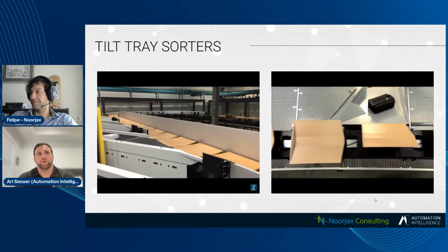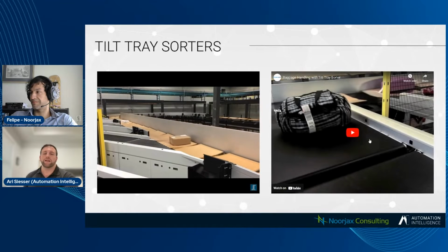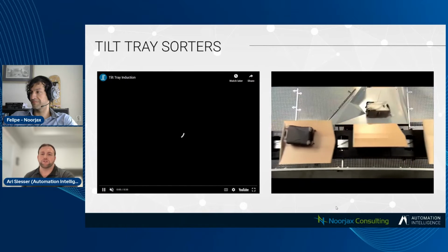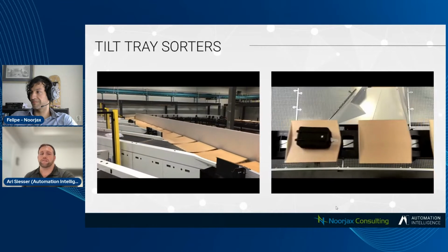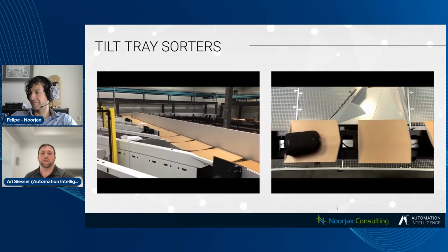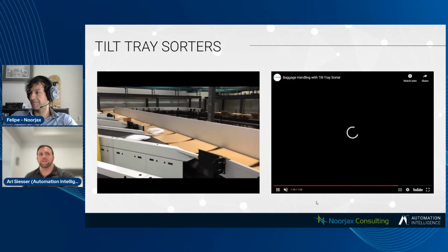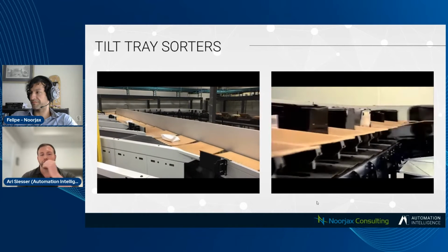So somebody's got to pull a suitcase out. So depending on the speed of the conveyor and the size of the object, that can be anywhere from 1 to 4 trays that need to pass between successive discharges to that same lane. And that's important because anytime you have 2 parcels that are going back to the same destination, those parcels will recirculate and block new parcels from entering the system.